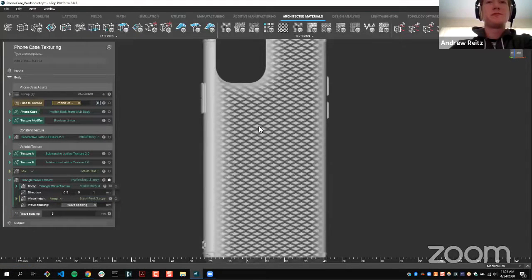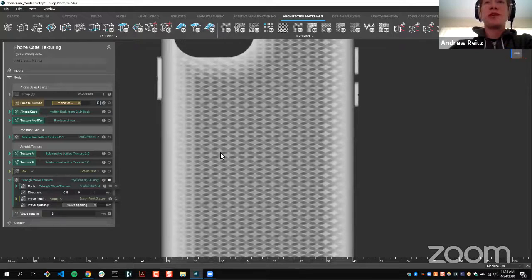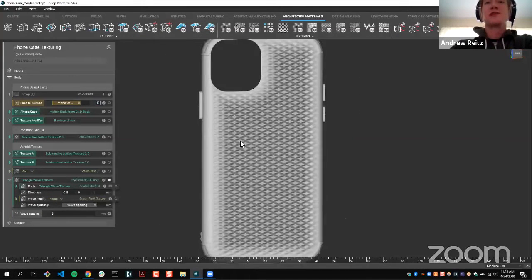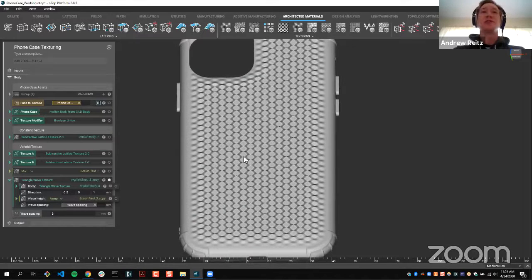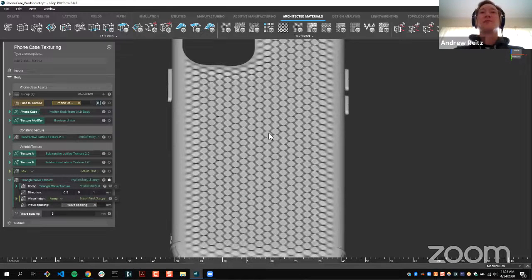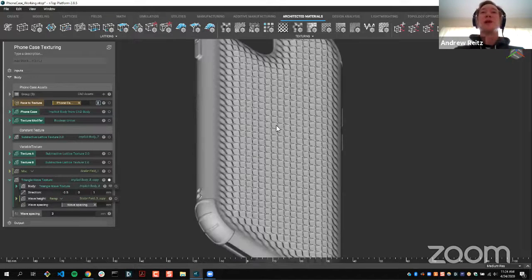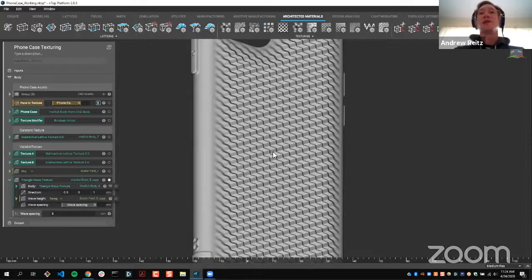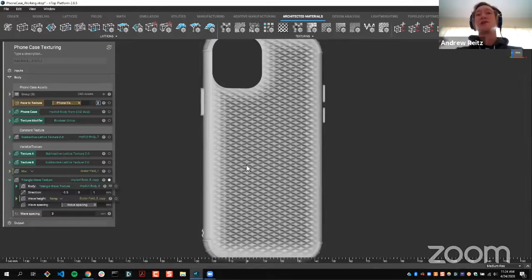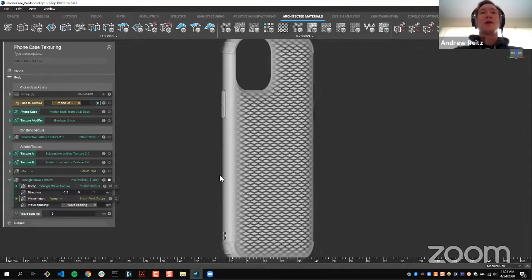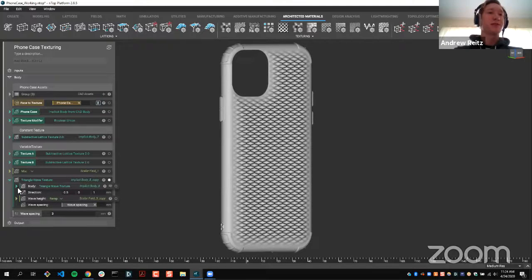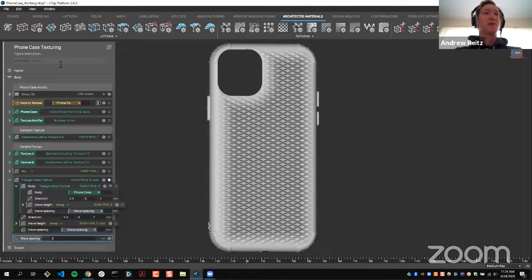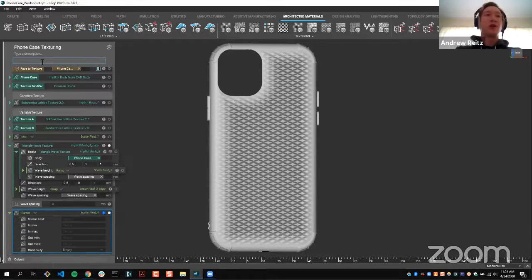Nice. The very last thing I'm going to show you, to turn this into something that's very visually dynamic and maybe a bit more functionally dynamic too, is to increase the wave spacing in the area where you may have the most contact from where you're holding the phone case, and have it be much smaller in these other areas. The variable we have at our disposal is the wave spacing, so I can make that a scalar field as well. I'm going to add a point variable.